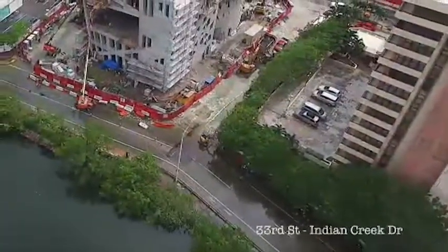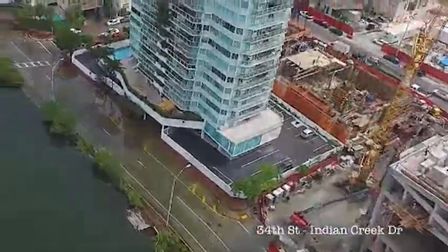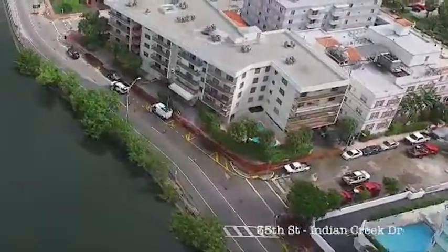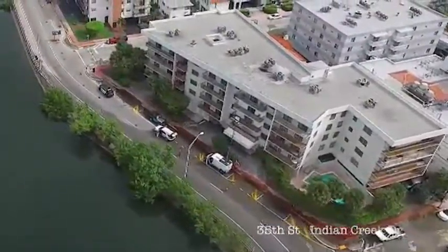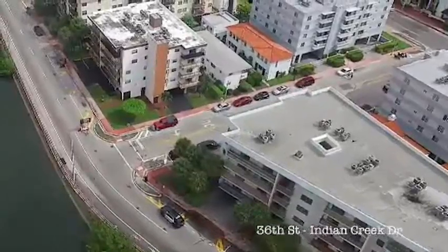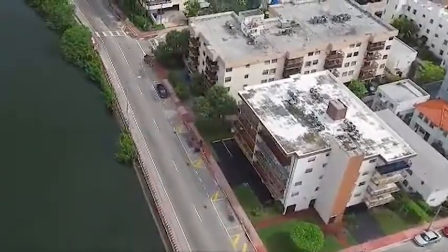So FDOT is working together with the city of Miami Beach to put in place, number one, reconstructing the seawall, raising it from the substandard elevation of 0.5 to 1 foot NAVD to 5.7 NAVD; reconstructing the roadway, which lies mainly at elevation 1 to 1.5, all the way to 2.7; building the 50,000 gallons per minute pump station; and providing drainage to this mile stretch facility from 25th Street to 41st Street, which will also provide drainage to the parallel roadway, Collins Avenue, another state road facility. We're talking about over 40 acres of drainage contribution.